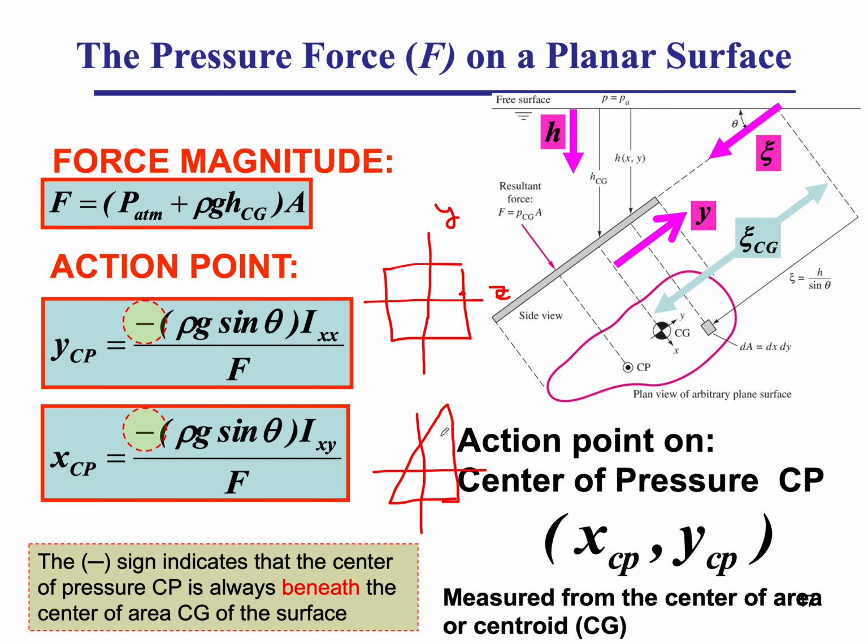However, if now I have my x-axis, my y-axis, and I have this triangular area, if I put my finger here and I try to push into the page, because I'm trying to rotate this thing around the x-axis, I will also get a tendency, so I will rotate around the x-axis, but at the same time my object will also rotate around the y-axis.